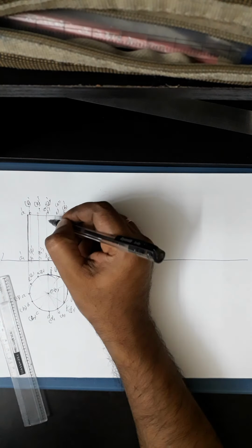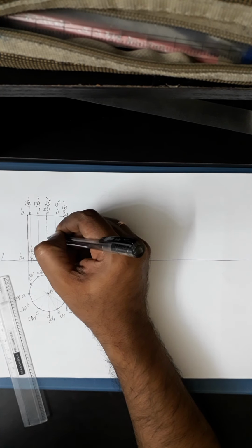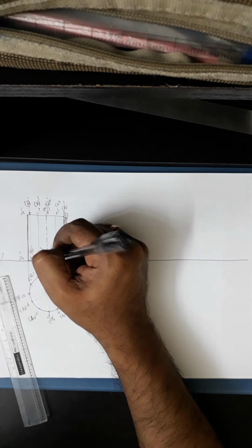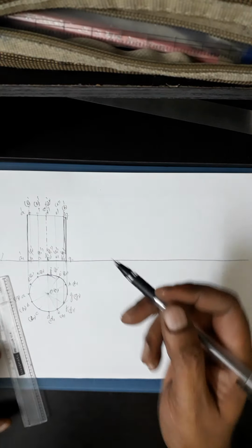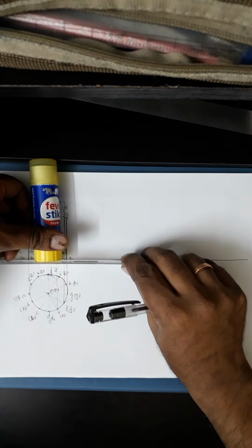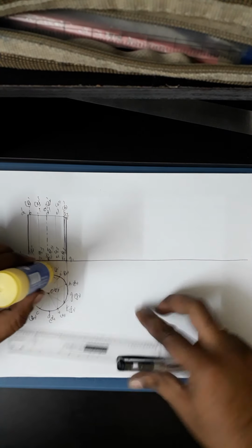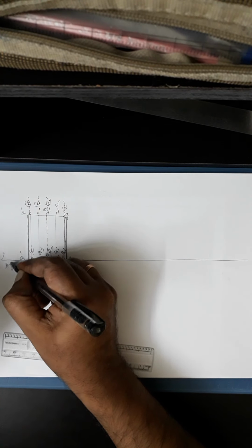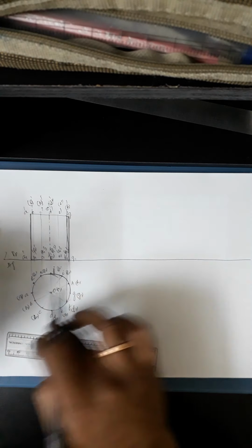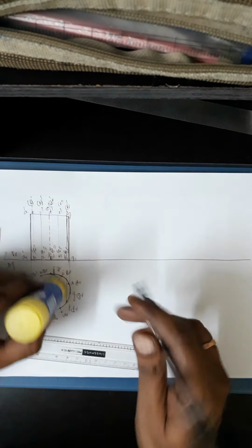So anyway, all should be very thin lines. You can represent the axis, because imagine a line now will be a very thin line, so you can represent this with a medium thickness axis line, right? I told you this is the position when it is resting on HP. If you take this as HP, then it is resting on HP. In the front view it can look like this. In the top view, if this is the horizontal plane and this is vertical, then this is the view. The top will look like a circle because the axis is perpendicular, whereas here the axis is parallel to VP.